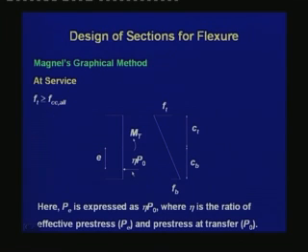At service, the prestressing force is denoted as eta times P0, where eta is a fraction of the initial prestressing force which has reduced due to the long term losses, and Mt is the total moment due to the dead load and live load.